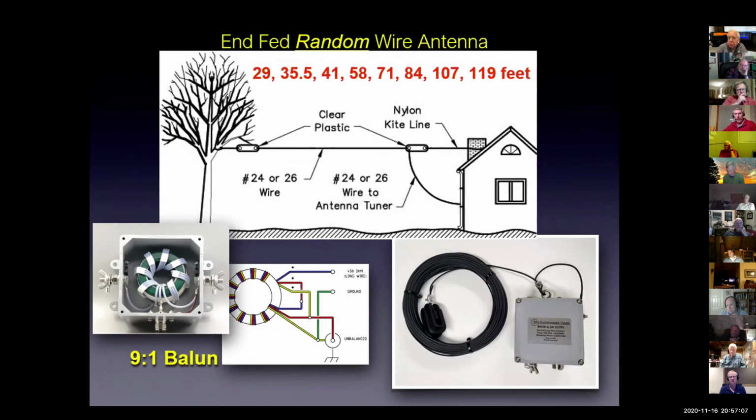So I'd try 15 meters and 10 meters and 40 or whatever. Sometimes it would tune up pretty well, and I was just kind of getting lucky, really, between the way the antenna was formed and the length of the transmission line. It worked out that the radio saw an impedance it could handle with its antenna tuner. But then I hit other bands where the impedance was so high the antenna tuner couldn't handle it.